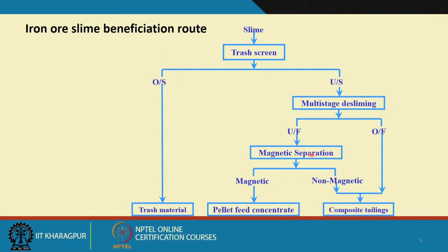Now, whether you should use magnetic separation or flotation here depends on many other factors. That is, what is the cost of the flotation process, what is the effectiveness of the flotation process, how much water will be required, and the same thing I have to look at for magnetic separation processes. The pros and cons we have to always compare.